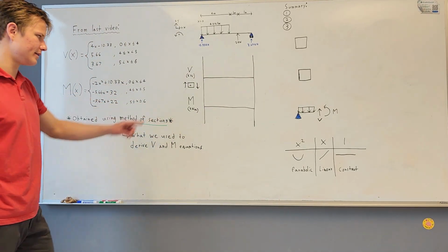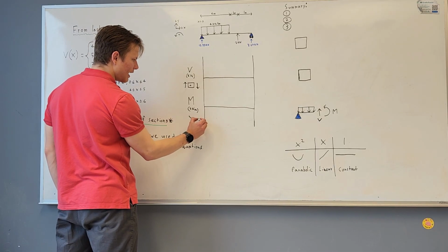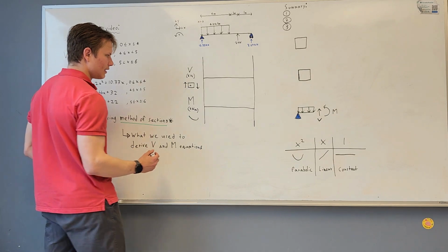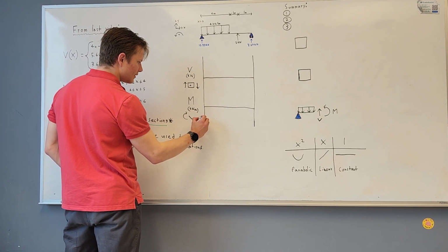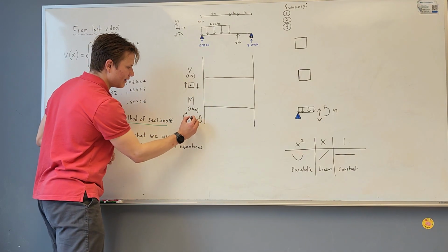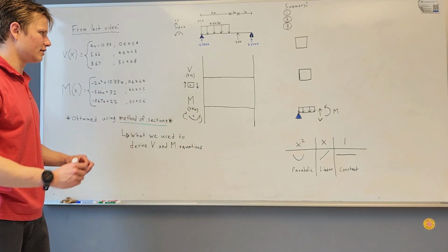And then for the moment, we draw a smile typically to show a beam that is bending upward. And then we will have 2 moments that are pulling this beam up into a smile with a positive right there to indicate that this is the positive sign convention.